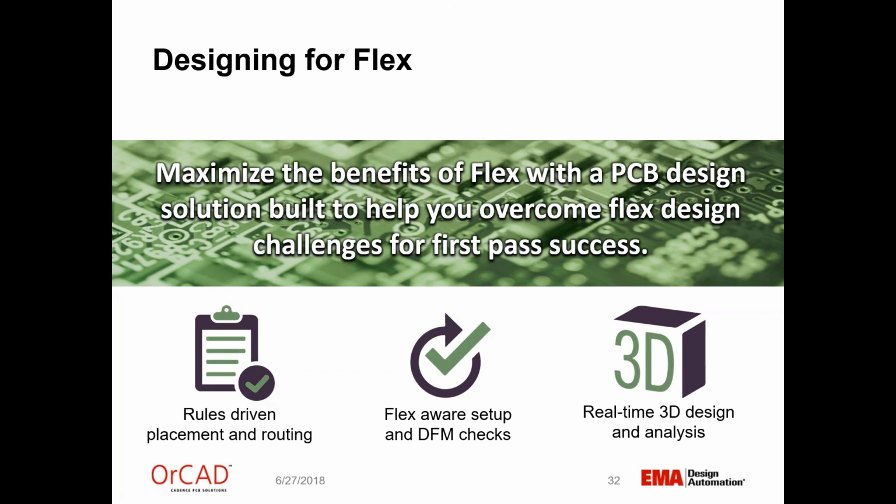How can one change a large number of pad stacks to adjust pad sizes depending on region? You can change specific pad stacks. What I would probably do though, instead of going in and changing pad stacks, is have an alternate footprint that would be used in that zone that had the correct pad size that you wanted. And in the case of vias, you can assign vias in region rules.